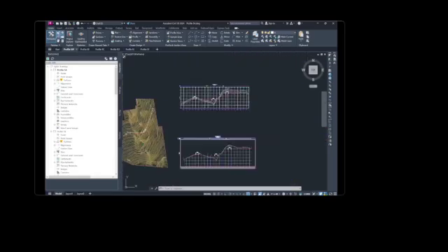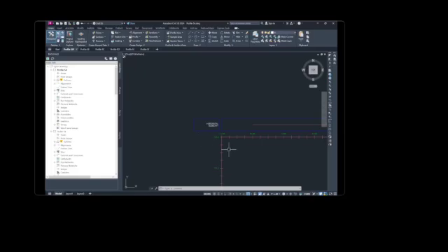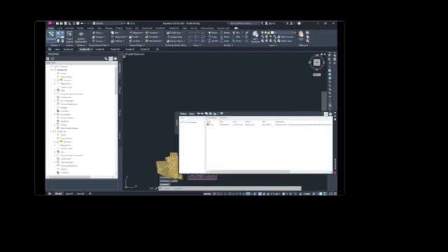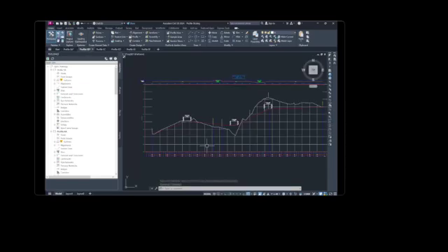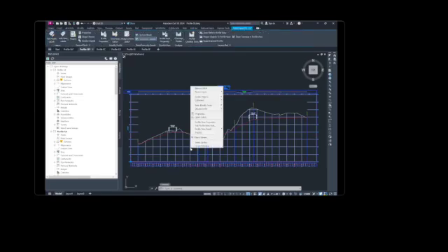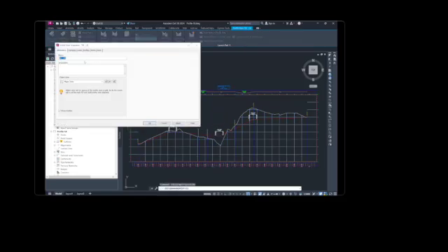We're going to go to exercise number 2, adding hatch patterns between profiles. Access the profile view properties. Open profile 5B. Click the profile view PV3. This is PV3. Right click and click profile view properties.